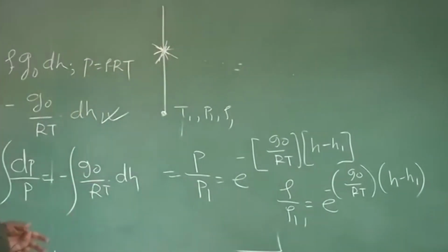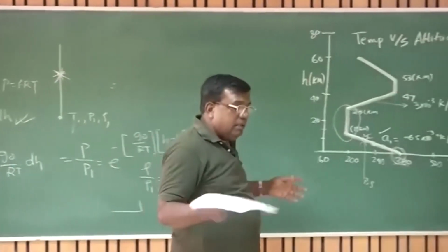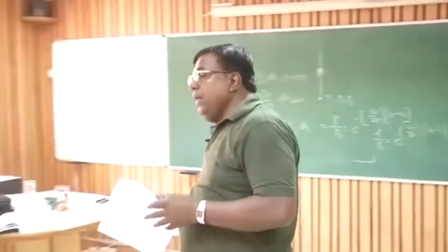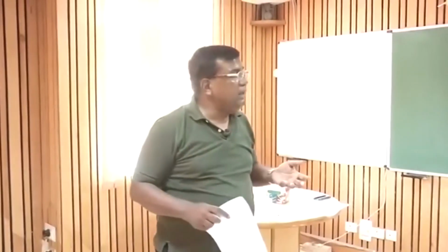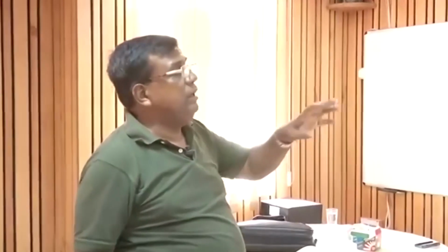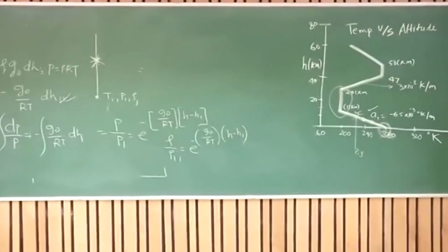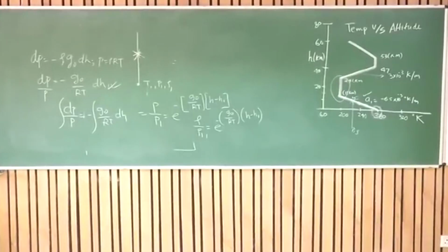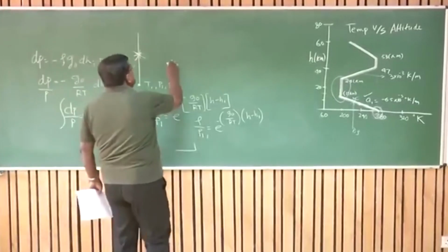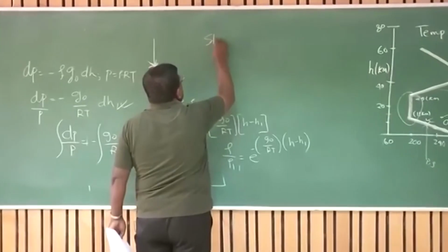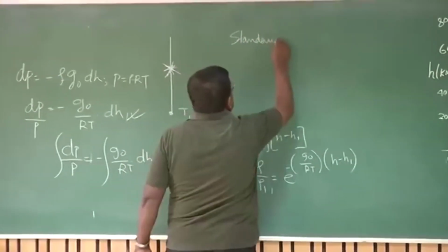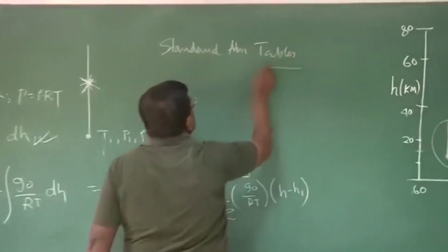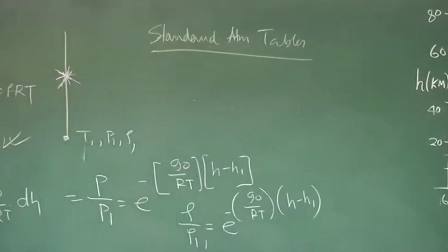So what is the message? Message is, if I want to create the atmospheric description in terms of a thermodynamic variable, I need to identify whether we are looking in a region which is governed by the gradient or by the isotherm. And then I apply this relationship, and in practice you will find there will be standard atmosphere tables available. They are generated using this relationship, right?